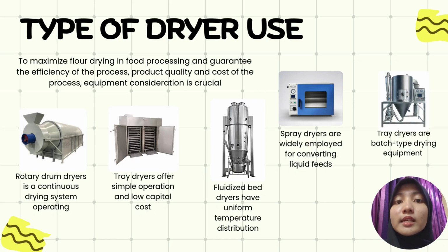thermal sensitivity is essential. Fluidized bed dryers are the gold standard for standard flour production, because they suspend particles in an upward airflow, ensuring rapid, uniform heat transfer and preventing clumping. For massive industrial scales involving coarser material, rotary drum dryers utilize a tumbling cylindrical mechanism to achieve high output, but they are less suited for delicate specialty flours.